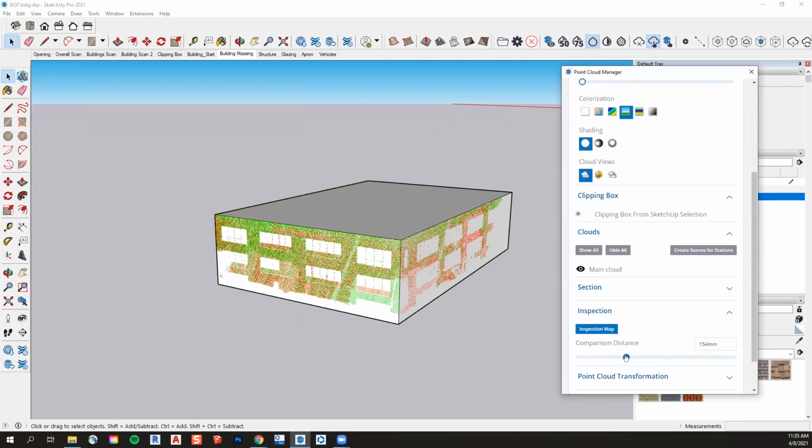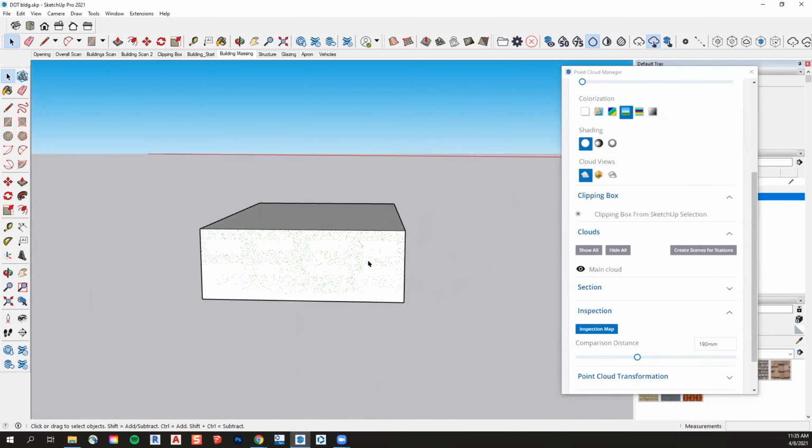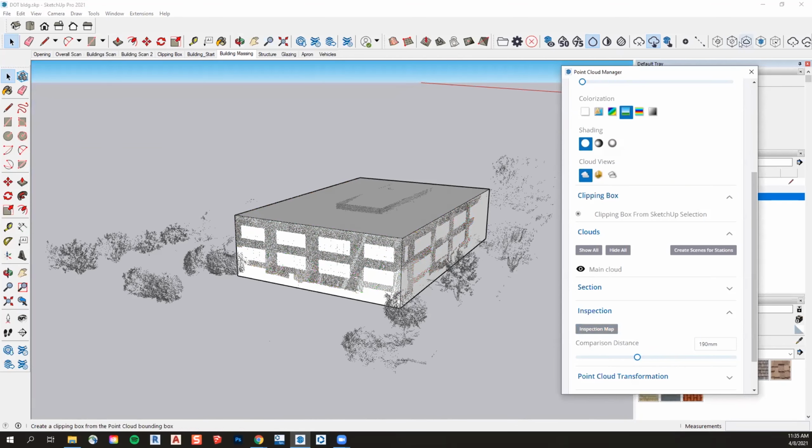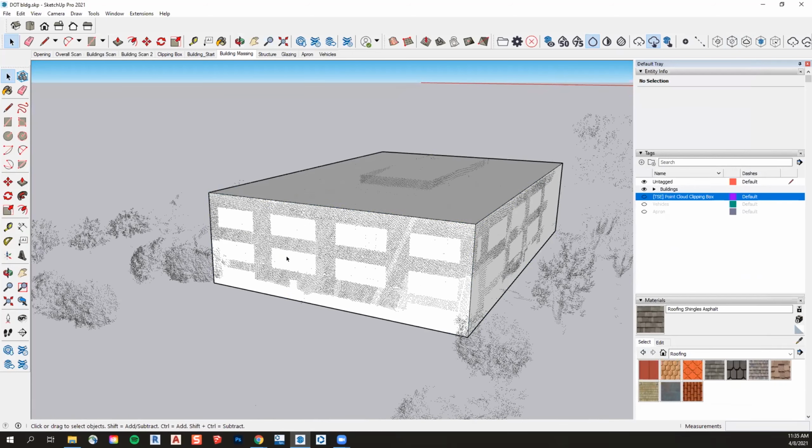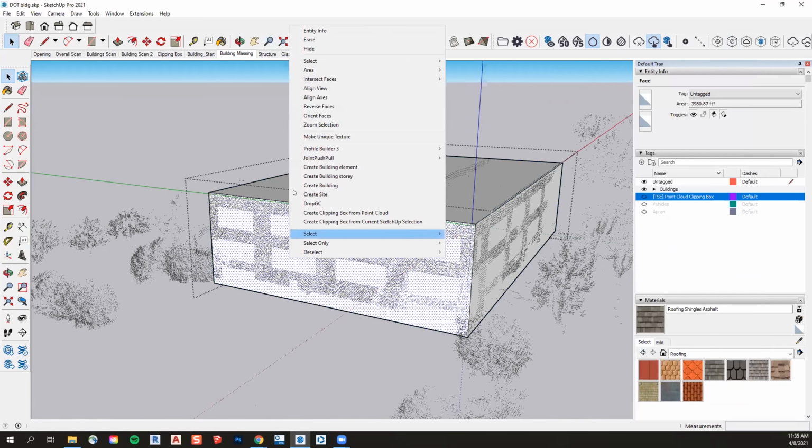So I'm pretty happy with how detailed my footprint is now and how it's lining up. Everything is pretty good. I'm going to turn that off. Now that my boundaries are good enough, I can add some detail as needed to visualize my project properly. So I can see pretty clearly in this scan, there's some good openings for the windows, and there's also openings into the parking level. So I'm going to change my view a little bit to better model these window openings.